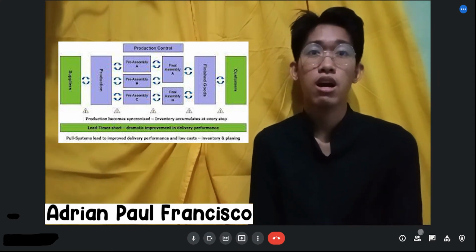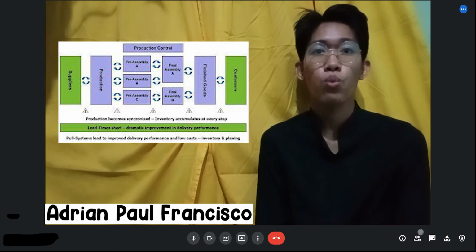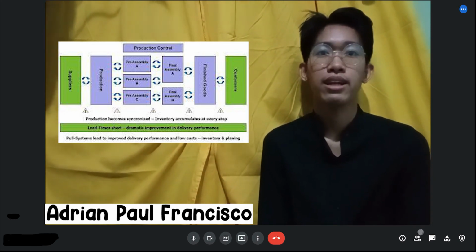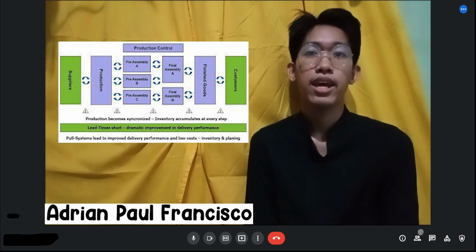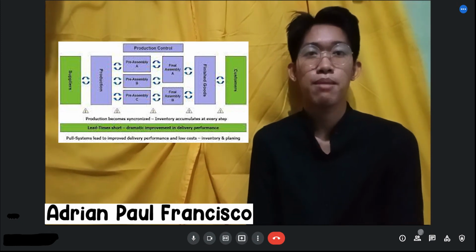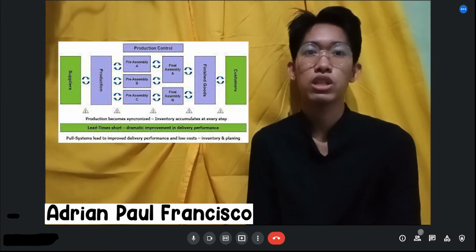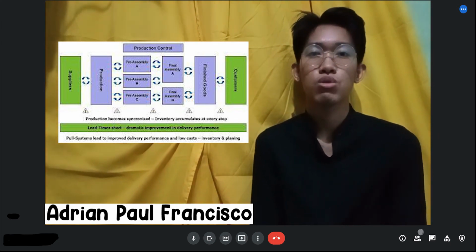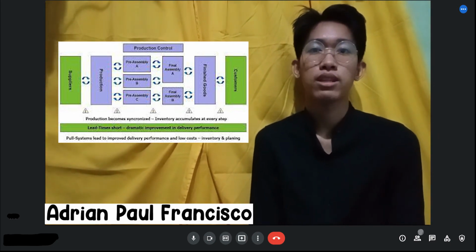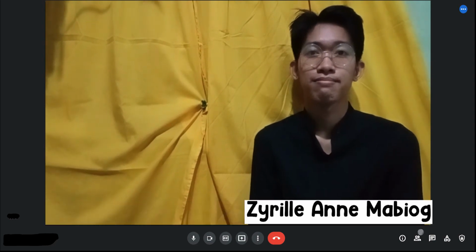In this situation, a card corresponds to one container of parts, which the upstream process will make for the supermarket ahead of the next downstream process. In a large batch situation, for example, a stamping press with very short cycle times and long changeover times, a single Kanban is used to trigger production when a minimum quantity of containers is reached.